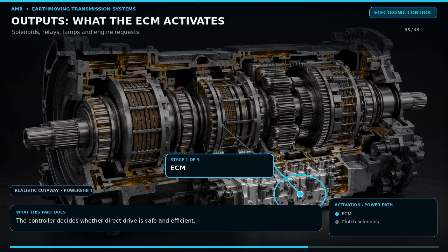Controller outputs are the actions that make the transmission respond. On a power shift, outputs include direction clutch and speed clutch modulating solenoids, lockup solenoid, lubrication or bypass valves, retarder valves, and parking brake release solenoids. On a hydrostatic machine, outputs include left and right pump displacement, motor displacement, brake release, and flushing or mode control solenoids. On an electric drive, the controller commands inverter torque and coordinates contactors and cooling systems.